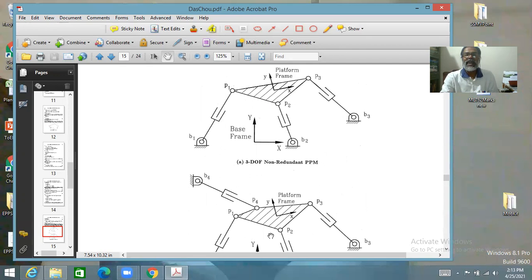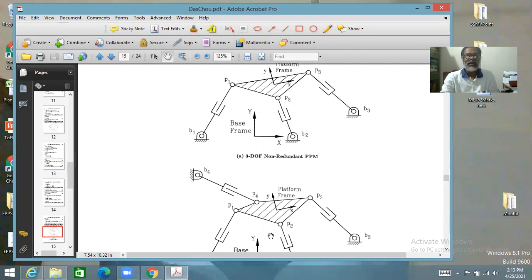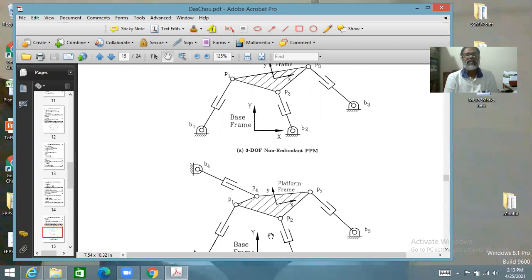Okay. Now this is a case of force redundancy, which I was talking about in the previous lecture. Rather than supporting the platform with 3 forces, you have the luxury of supporting it with 4 forces. And therefore, in order to solve for these actuator forces, you will typically have a system of 3 equations in only 4 unknowns. Therefore, infinite combinations of F1, F2, F3, F4 can successfully support it, and you can choose. That is the redundancy there.